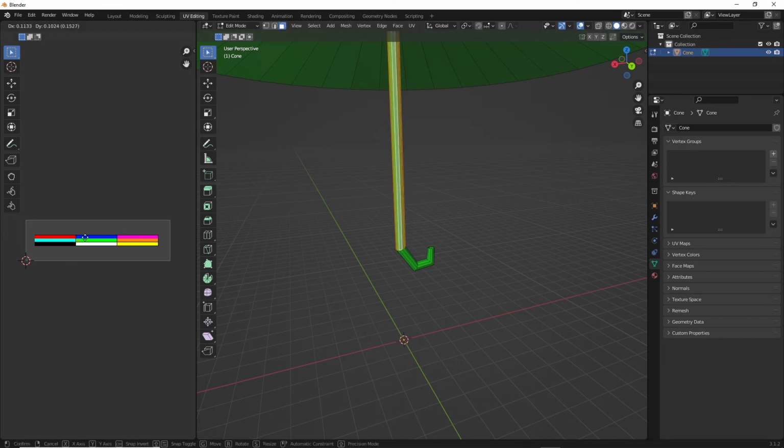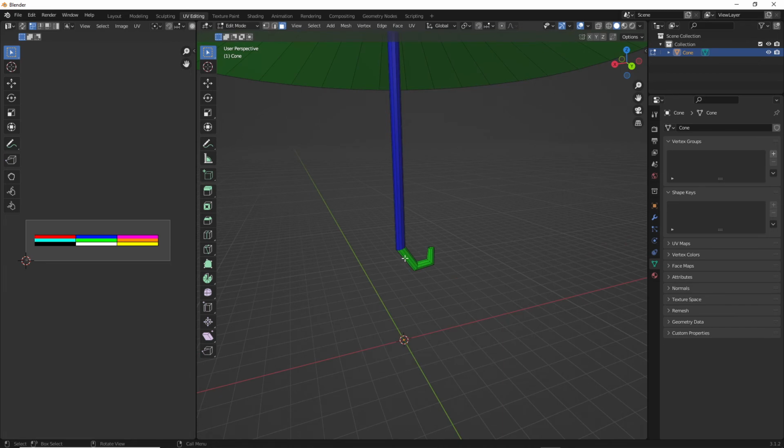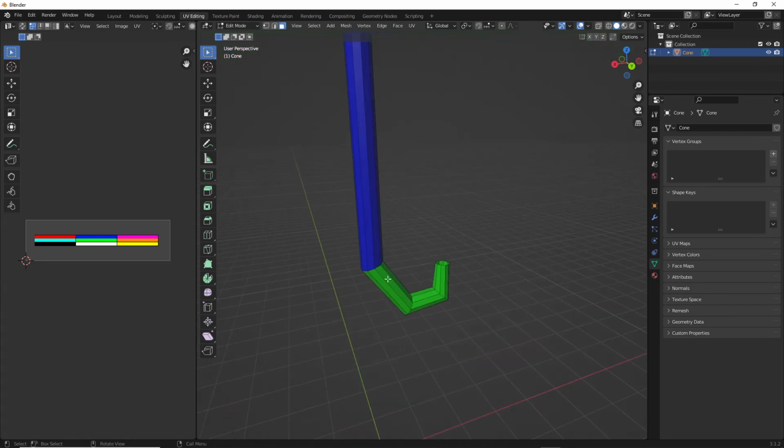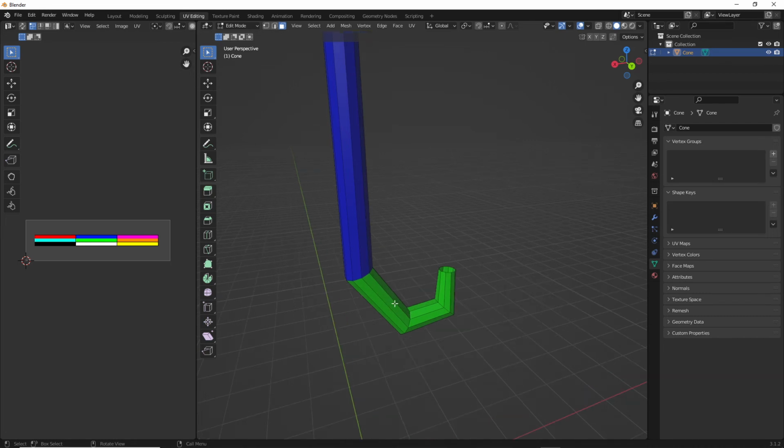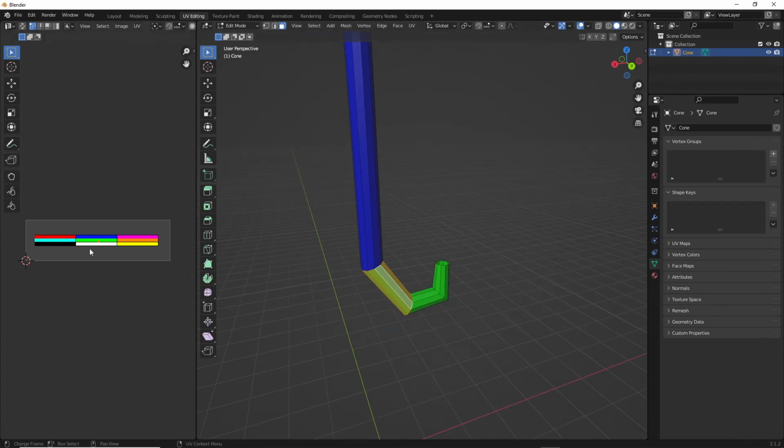Let's grab this again and set this perhaps to blue. A funny umbrella. And this one I set here to black perhaps. And how I make this, I press Alt and click the edge here. It makes a loop select again. And now I go here to the right, grab. Now I go to black here, and here another color.